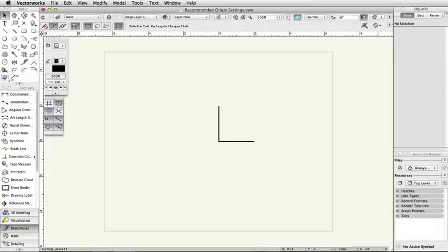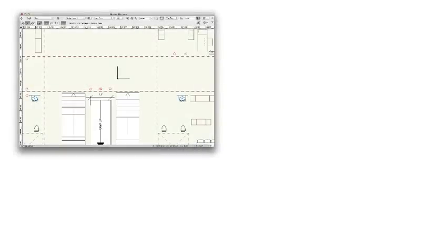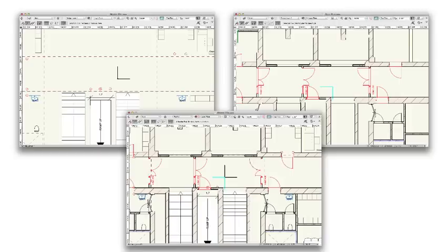When setting up your files, create a marker to indicate the Vectorworks internal origin. Here, I have used an intersecting vertical and horizontal line. This will also allow you to verify that the objects are aligned correctly. Also remember that the objects in all files should be as close as possible to the Vectorworks internal origin.